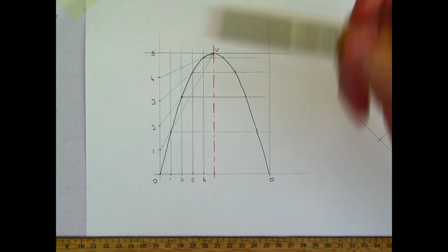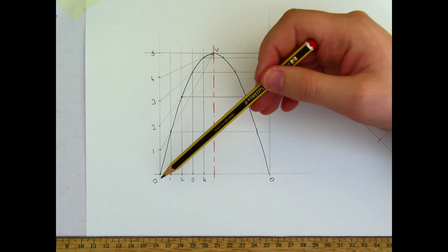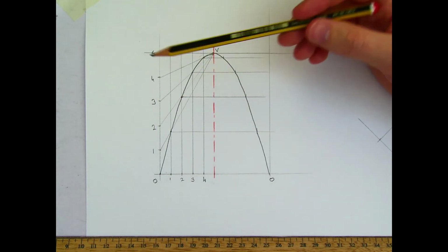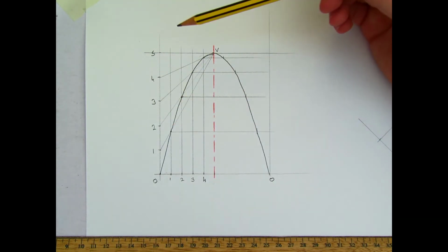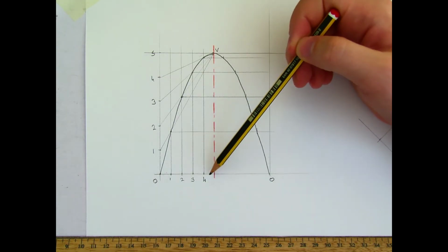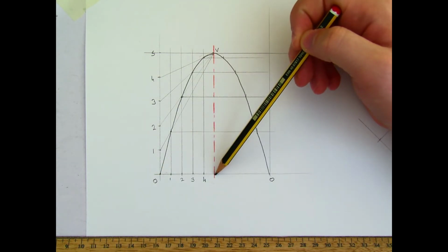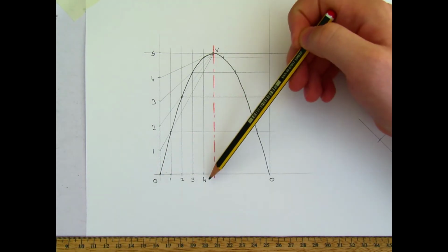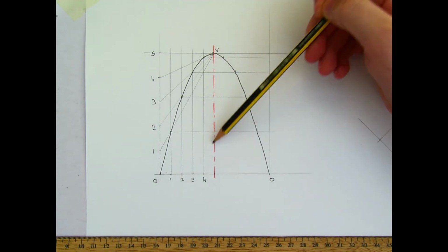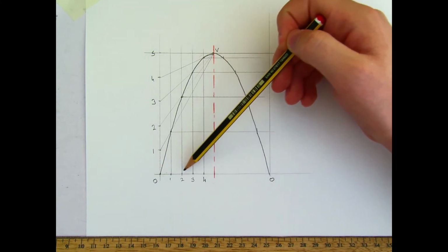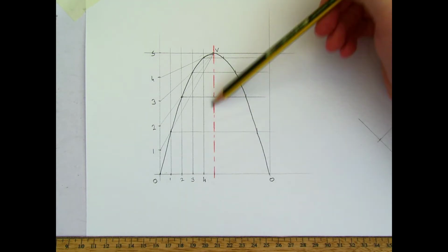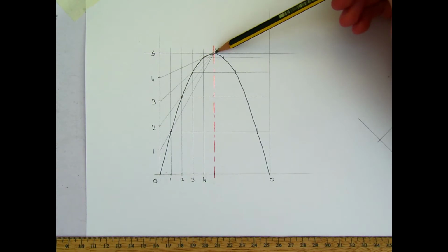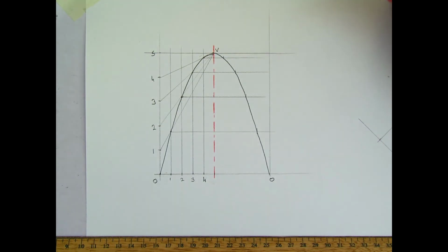So just a quick recap. You need to divide the sides up into the same number of equal parts. If they don't divide in evenly, use the construction for dividing a line. So dividing the line up into the same number of equal parts. On the edge of the rectangle that intersects the axis, you go parallel to it, and the ones that are already parallel to it, you join to the vertex. So that's the first part of this.